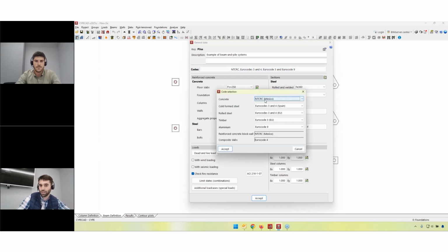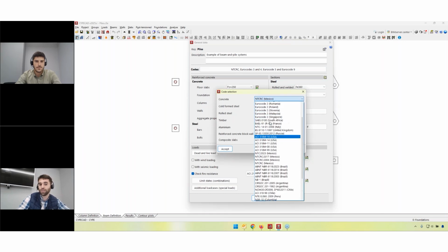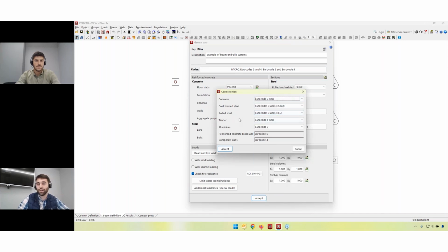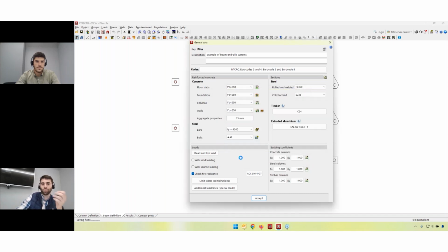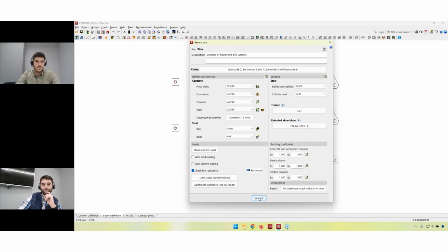Okay, thank you. In case the Eurocode is defined, the safety factor, let's say a more efficient way of calculating the piles, would be around 2.2. This is what we have calculated in comparison to the safety factor of 3. So it's a more sophisticated approach to calculating a pile, but it also has to take less safety measures as a consequence. So we apply the Eurocode 2.